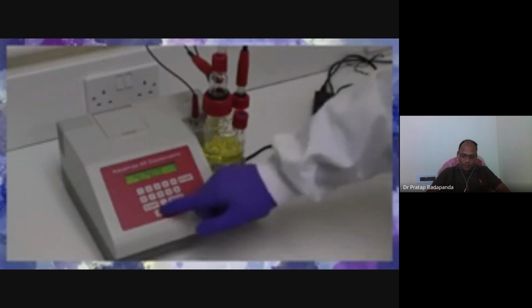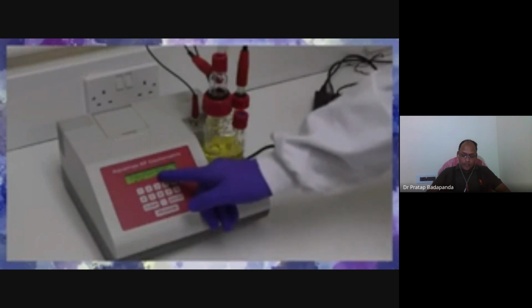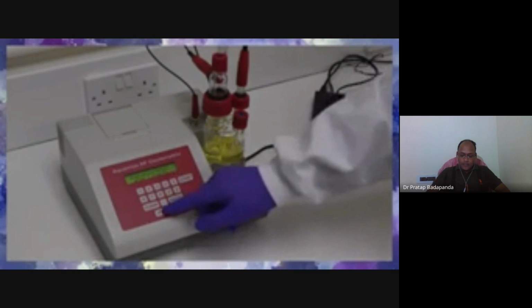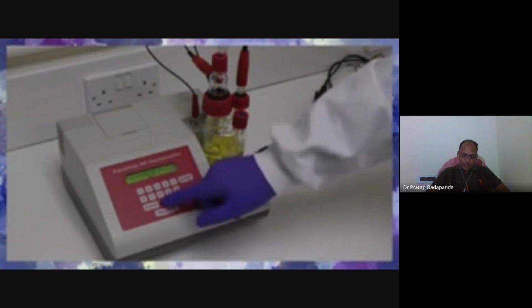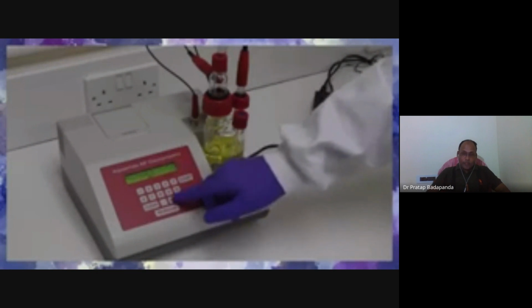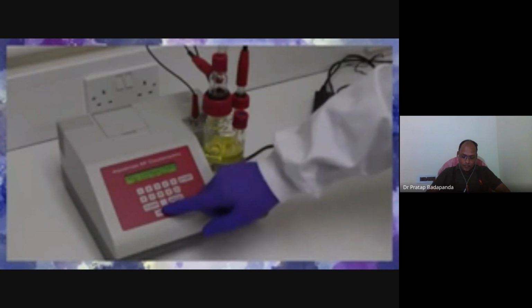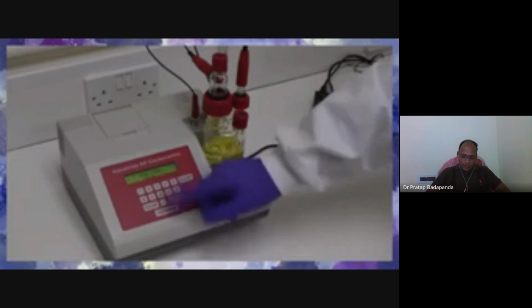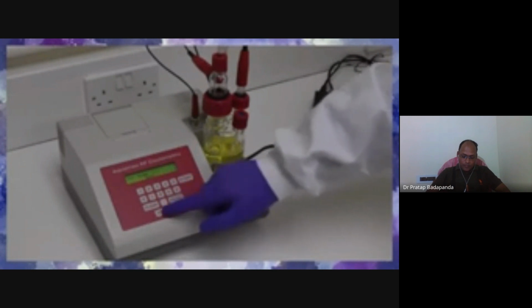The statistics print parameter will print statistical data from a series of up to 99 results. The background drift print option may be either on or off. Other parameters allow delay times to be programmed, minimum titration times to be set, and the sensitivity to be changed. The beep can be turned off, set to sound when a key is pressed, at the end of titration, or both.